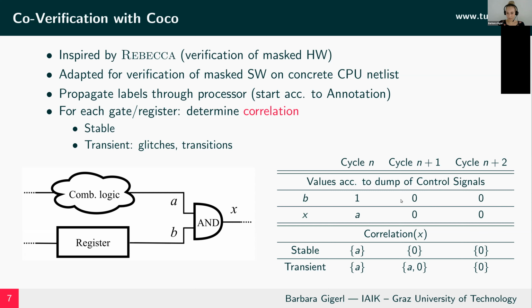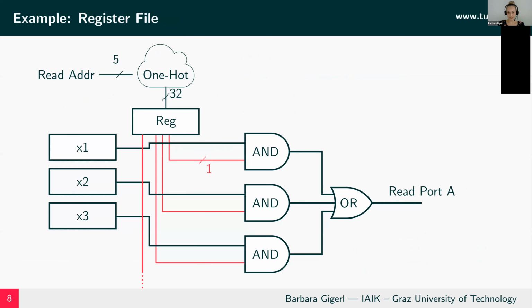And this is a quite nice concept which we also applied to the register file. So to construct a secure register file, which you see here, we placed a gate before each register, and this gate determines if we will see the register value at the gate output. And as a gate value, we use the one-hot encoded register address. So in this register here, at most 1 bit will be 1. And this refers to the gate being open and we want to read the register.